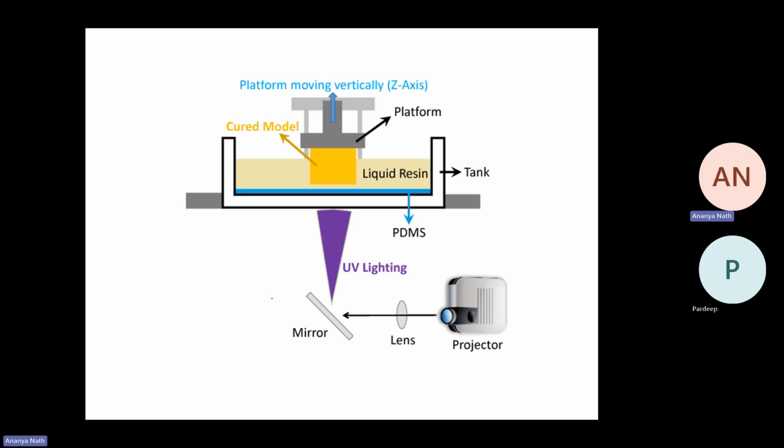So it's the wet photopolymerization process, where the liquid resin is the raw material. The resin is a kind of polymer. So in this process, you can only print polymers. The polymer has to be in liquid form. Mostly resins are printed using this process. So we use thermosetting type of polymer.